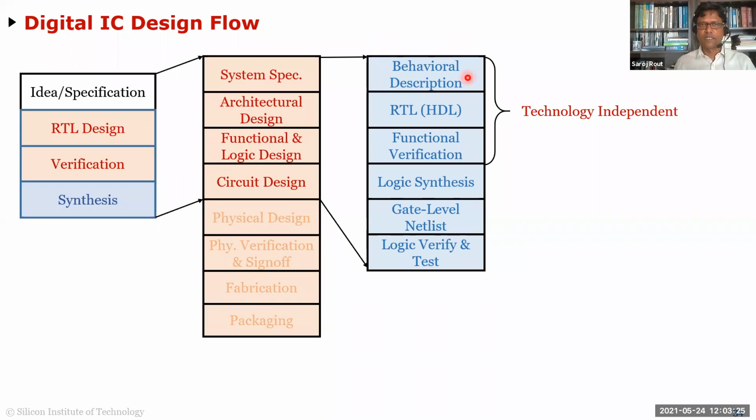So in this behavioral step, you had a very abstract description of your design using C or C++ or Verilog-A or whatever, SystemVerilog. Now you're taking it to another level, to your physical step, which is RTL. So RTL is still behavioral in nature, but at least now it is event driven. If you write it in SystemVerilog, you can still have code which cannot be synthesized. But typically when you write RTL, you write what's called synthesizable RTL code.